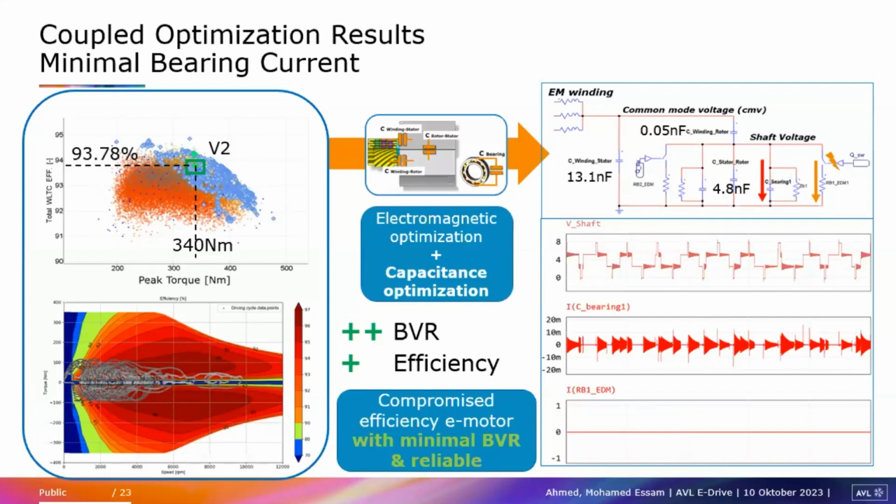How the capacitance changes usually needs a lot of intensive measurement and supplier discussions. Here the electromagnetic analysis was focused on the full driving cycle, and the capacitance was based on the insulation geometries and the active material geometries.